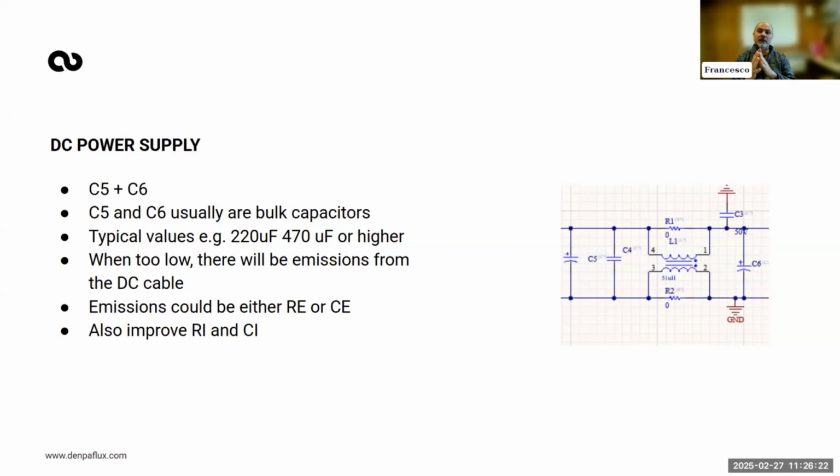Instead, ceramic capacitors work well above this frequency, but the value of these capacitors is usually much smaller than electrolytic. So the reason why you need electrolytic and ceramic capacitors in parallel is to have as wide a band as possible. You try to have a DC that works as a DC in the widest spectrum possible.